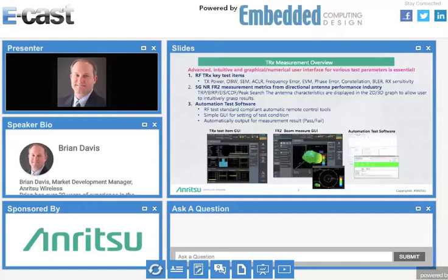So you really need to use a lot of the technologies and ways to test that the antenna industry has been doing for a number of years for performance verification. So total radiated power, peak beam search, those kinds of methods. Those are relatively new for a lot of the core baseband modem device makers that have traditionally been using sub-6 methods.